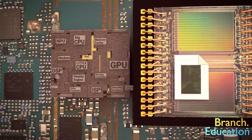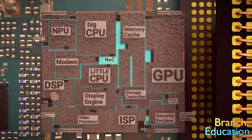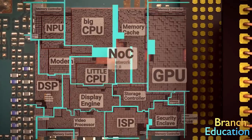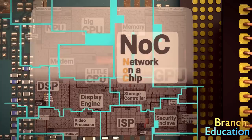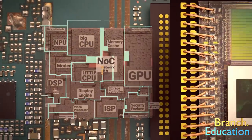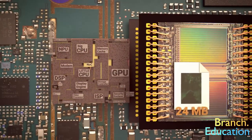First, the data path between the SoC and the DRAM is shared by everything. In this scenario, it's the job of the network arbitrator to prioritize the incoming sensor data of the uncompressed raw image so that no data from the camera is lost, and thus the arbitrator streams the raw image directly into the DRAM. Second, a 12 megapixel uncompressed raw image takes up around 24 megabytes.